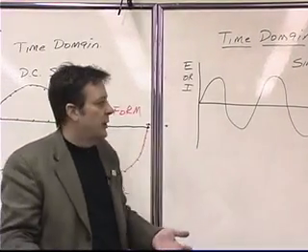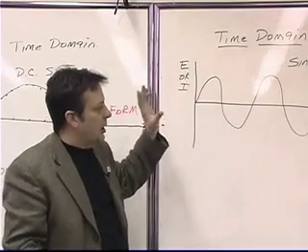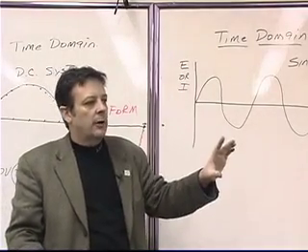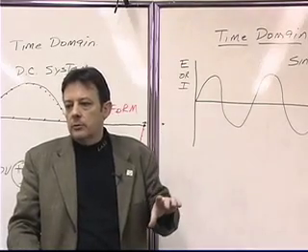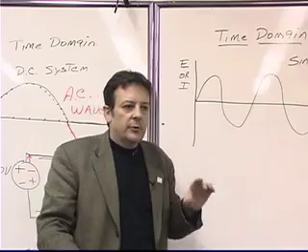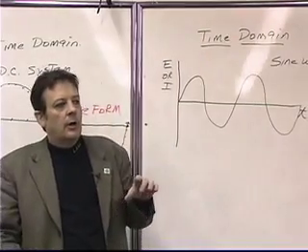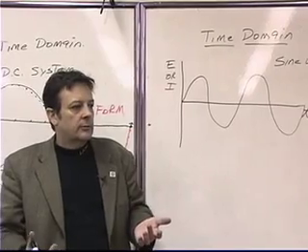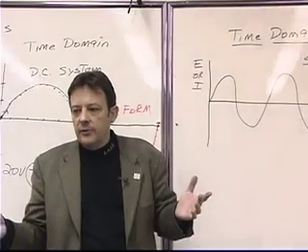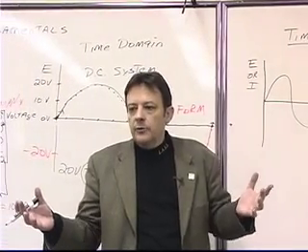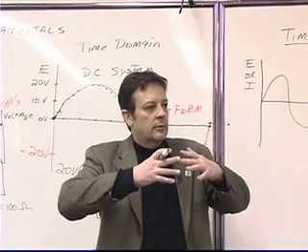Okay, so we're looking at the waveform coming off of a Honda generator that's generating 60 cycles per second. And 60 cycles per second is the predominant frequency that's used in the United States. The reason that everybody has to use the same frequency is because most all of the power grids are interconnected.